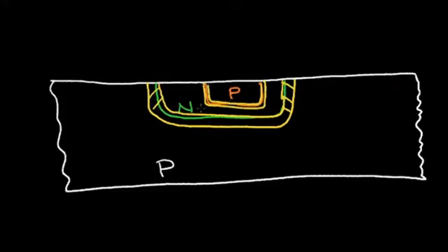Now I can just look at this wafer, this silicon structure, and I know that this P region is lightly doped, and this N region that I added has to have a higher concentration of dopants, and this P region that I finally add in must be the highest concentration of all. So I can look at this and I can know that this depletion region between this N and P region is wider, and it's wider because the concentrations are lower.